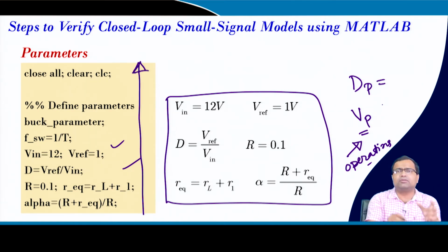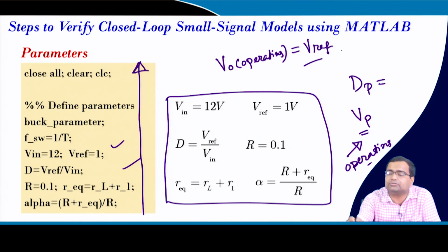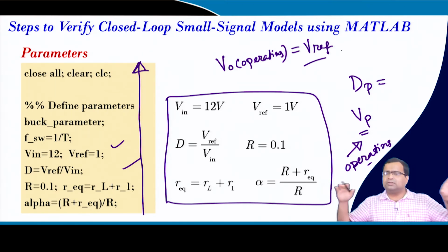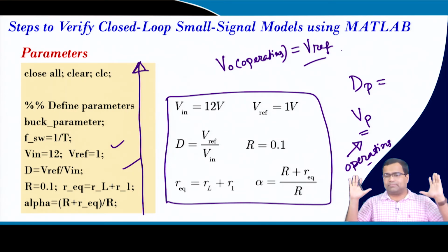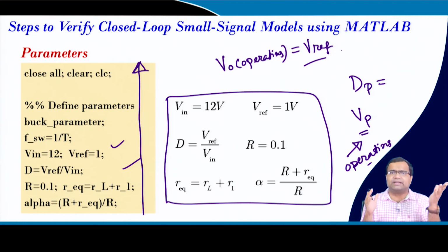But here we are doing closed loop control and we have an integrator. So, we can assume that our operating point V0 is nothing but Vref, where we are setting it, because we are using an integral gain, and you can assume that the average will come to Vref within a reasonable amount of time. Though they are defined in terms of the limit t tends to infinity, we will get close to the same value within a certain finite time.